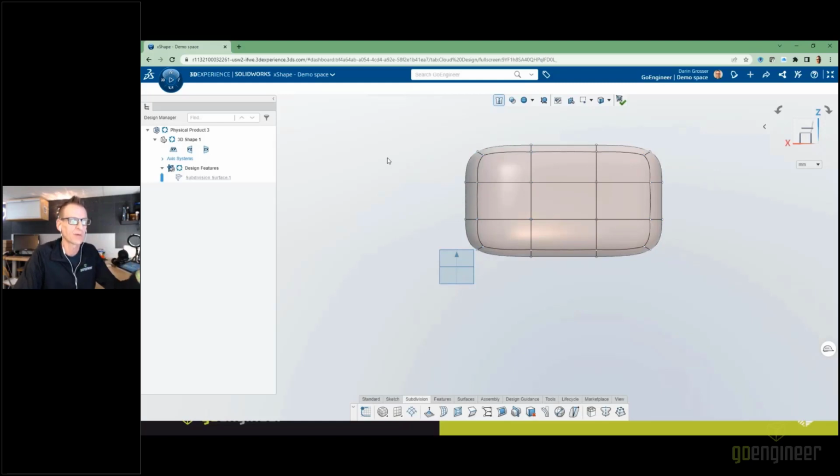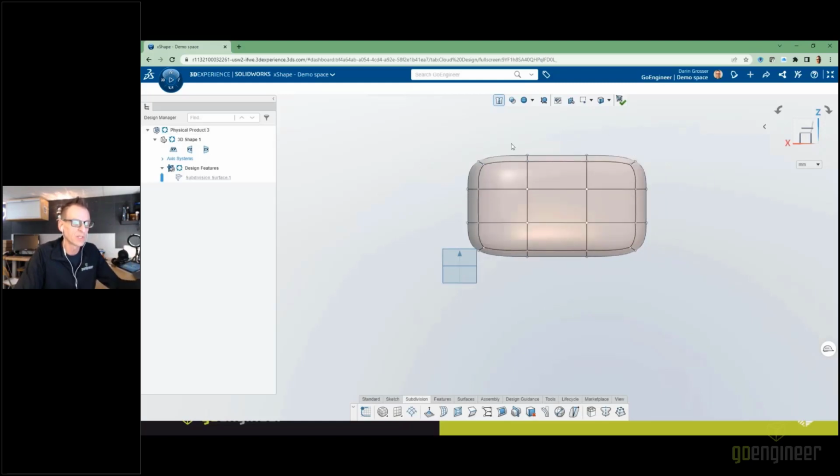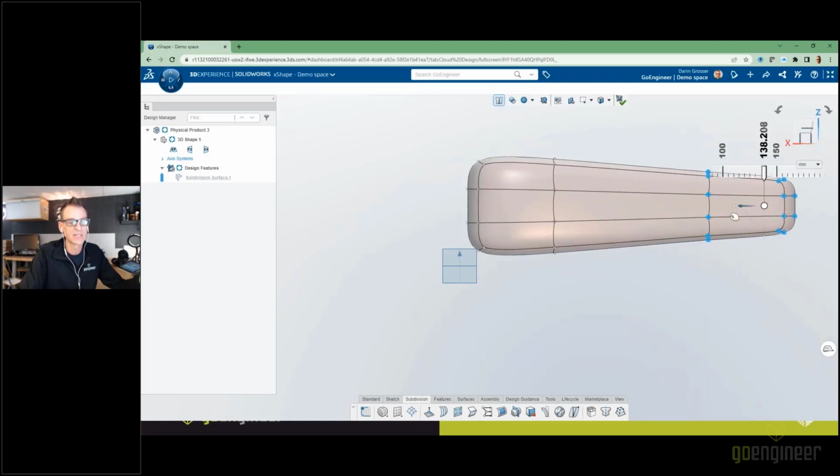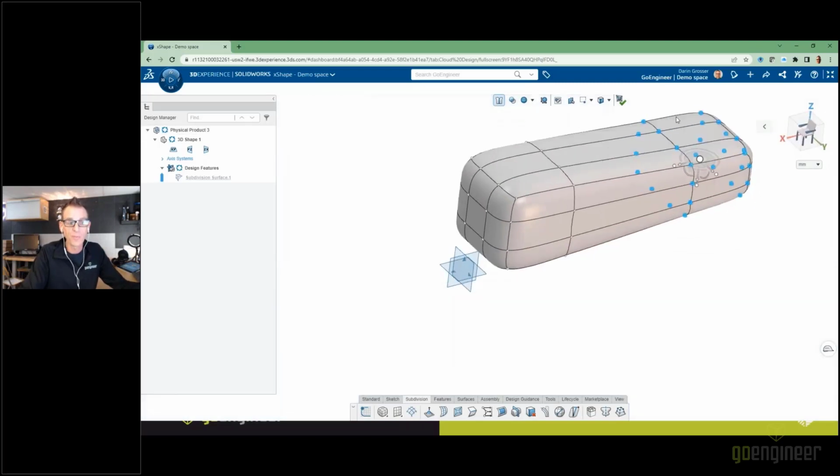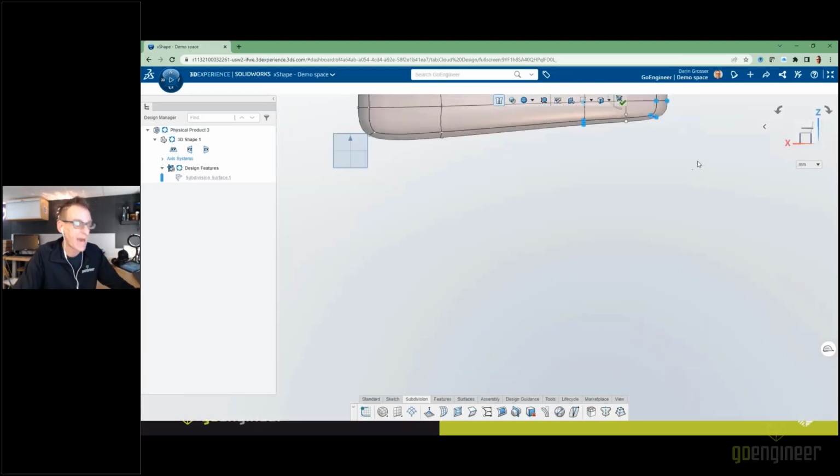Now I'm going to click in the background and deselect. And we're going to use a little bit of just more of an isolated or random selection here. Now with a basic window here, I'm going to select all of the nodes on all of the faces at the end of my body here. And as I go ahead and start to manipulate things, you'll see once again that only the things that are selected on screen are what happen to be actually moving. And right now we're selecting through the part, so everything I'm selecting on the front is actually selecting right through to the back.